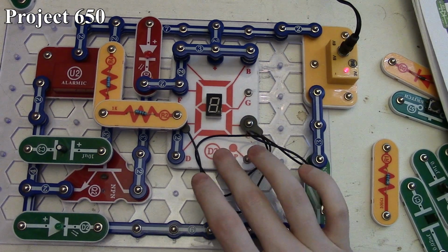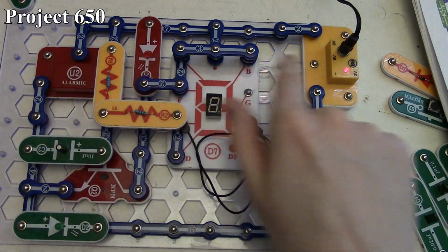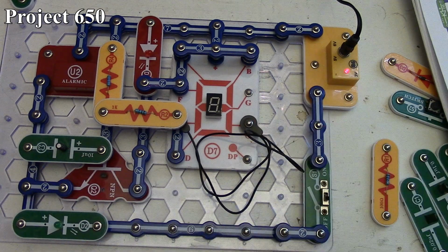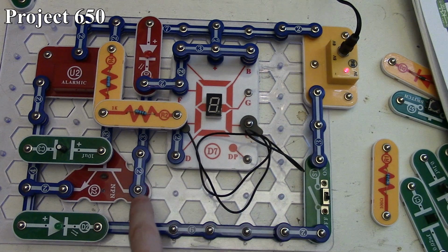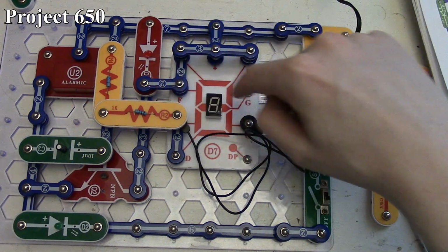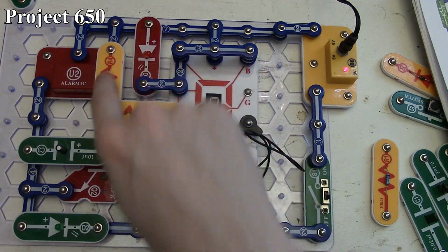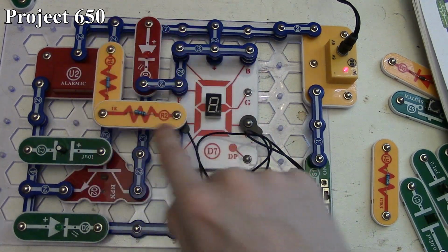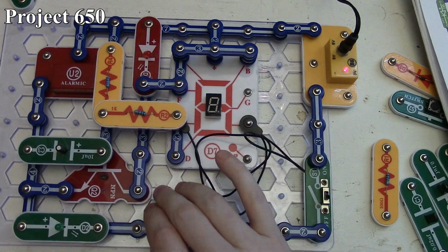So with this, we have our 7-segment LED again, and it's got a couple of different segments connected up here. Our alarm IC is being fed. We also, of course, have 6 volts powering everything. We have our red LED coming down to the collector of our NPN transistor, and that's connected again to the top portion of our segment LED. And then we have this set of resistors, both our R4 and R2 resistor, coming down and then connecting to the bottom segment of our 7-segment LED.